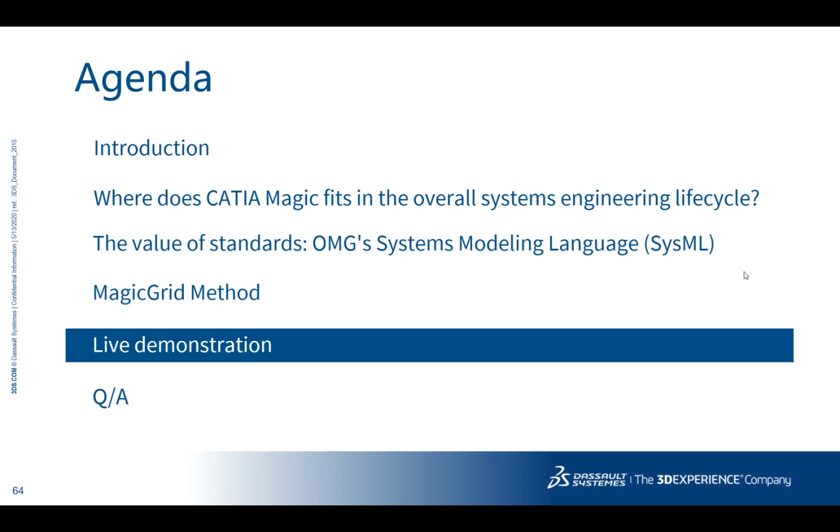Now it's demo time. And it is also time to introduce the modeling software as the third enabler of MBSE, which goes together with the already introduced language and method. Why is the modeling software so important? Because it provides the repository for storing models. Without the repository, SysML diagrams would be just separate drawings, as there was no underlying model behind them.